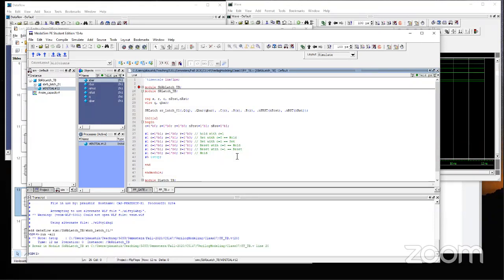With that, we have one more test bench, SR latch DB. Here we can observe a couple of things. It is hold with C equal to 1 because S and R are both 0. Set with C equal to 1 is basically set, and set with C equal to 0 is practically hold. Even if we are trying to set, since C is 0, it will be on hold, and that's also demonstrated in the reset part.